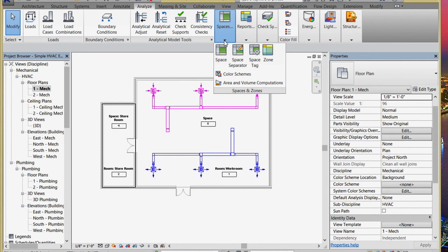It's interesting to think about subdividing in terms of this space versus that space. Since there's no real boundary between them, I'm not sure we can really get much useful data out of that. I'd probably just let it run all the way up. Although what we'll tend to do is, if you have a plenum system, the plenum will be a separate space from the room, and then let the mixing happen within that. Good concept though, but I'm not sure the model will really do much with it. Okay, next up is this notion of zones.